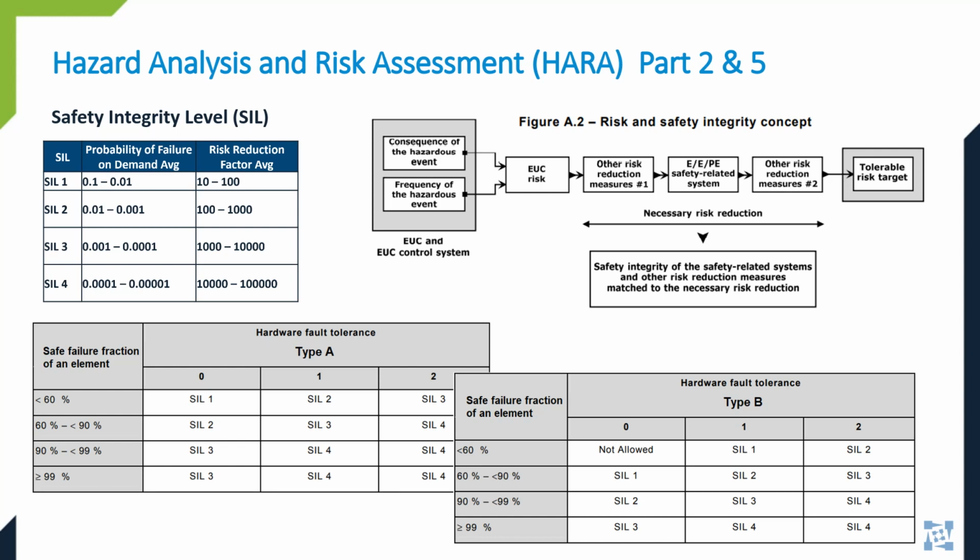There are several risk assessment approaches. A popular one is doing a failure mode and effects analysis using your requirements. Parts 2 and 5 of the standard provide guidance and examples. The analysis results will also place your device at SIL 1 through 4, SIL 1 having the least consequences if failure occurs, and SIL 4 having the greatest consequences if failure occurs.